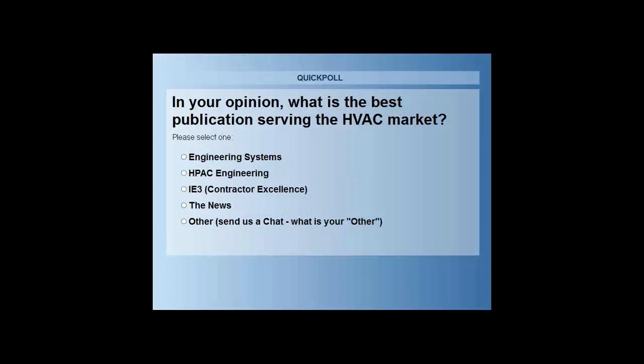Lisa, let's take another question from the audience as well. The next question is, what do I tell an inspector or AHJ who questions the installation in a packaged rooftop unit? Okay. Well, first, the principal operation of duct smoke detectors is the pressure differential between the sampling tube and exhaust tube.